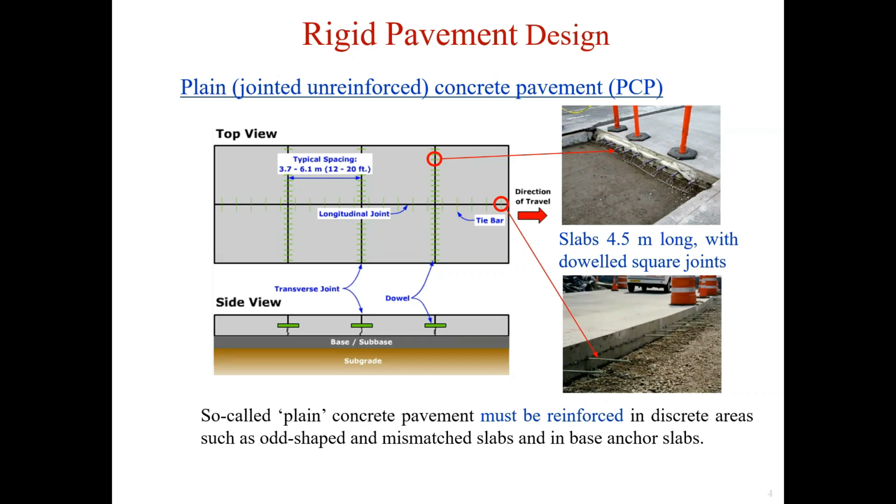The dowel bars are placed at the transverse joint of concrete pavement, and they take part in partial wheel load transfer from one slab to its adjacent slabs. The dowel bars allow actual thermal expansion and contraction of the concrete slab along the axis of the dowel.